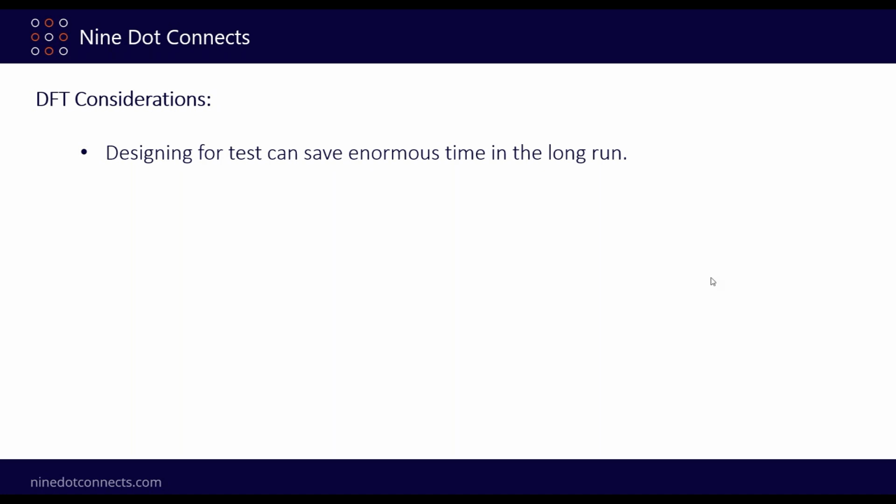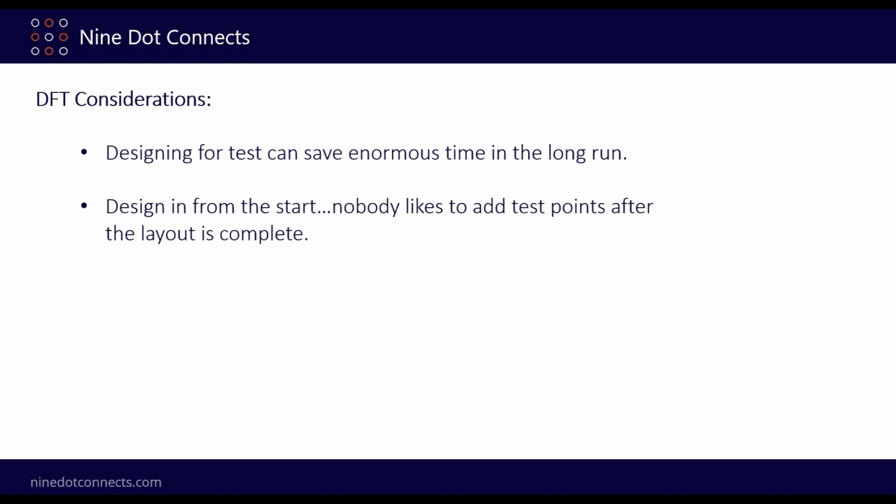So design for test can save enormous amounts of time in the long run. And it's something that a lot of people don't think about at the very beginning of a design, right? When we put down that first part on our schematic, we're not really thinking about testing that board yet. So starting at the very beginning is very important. And nobody likes to add test points late in the layout. It's always a bad thing.